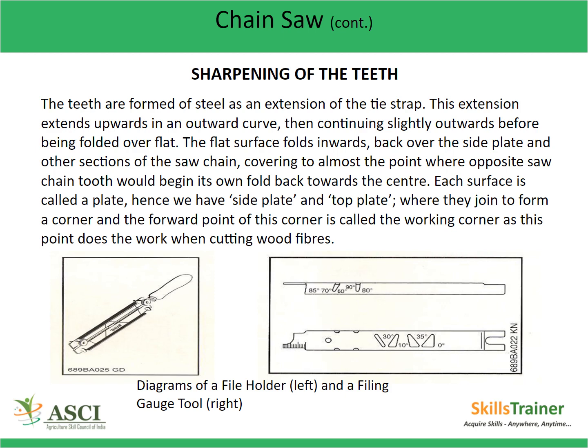Each surface is called a plate, hence, we have side plate and top plate, where they join to form a corner, and the forward point of this corner is called the working corner, as this point does the work when cutting wood fibers.